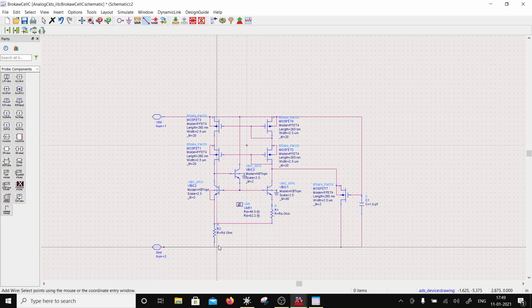Right, so everything is very simple right now. The resistance is halved, and the reason for that is that in this branch the current is going to be twice IPTAT. That's why this resistance got halved. So the difference between the regular band gap circuit and this Brokaw cell is that this is seeing twice the current, twice the IPTAT. That's why its value got halved, and the RS value is almost the same as what it was. So we just slightly adjust these resistors and got the band gap.